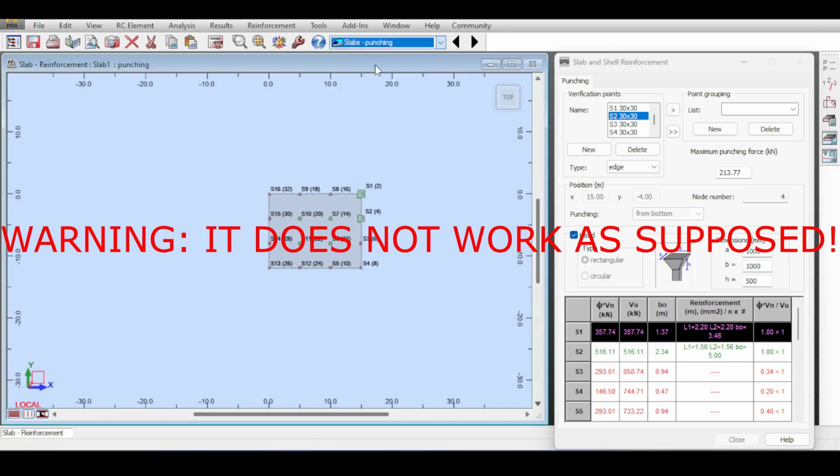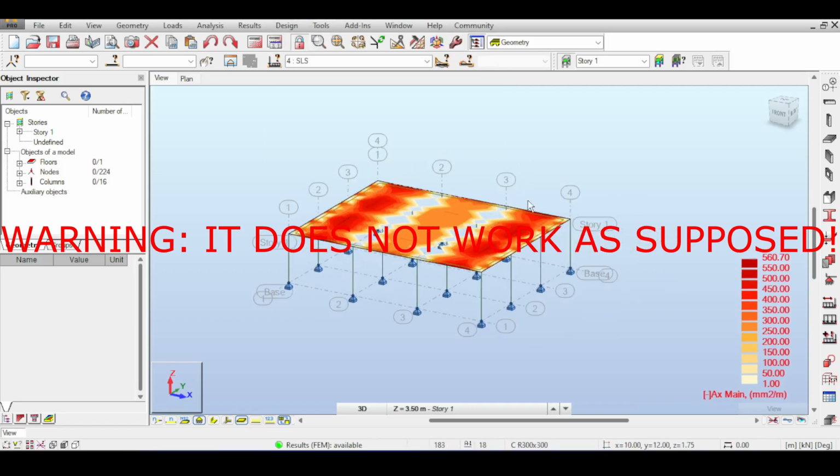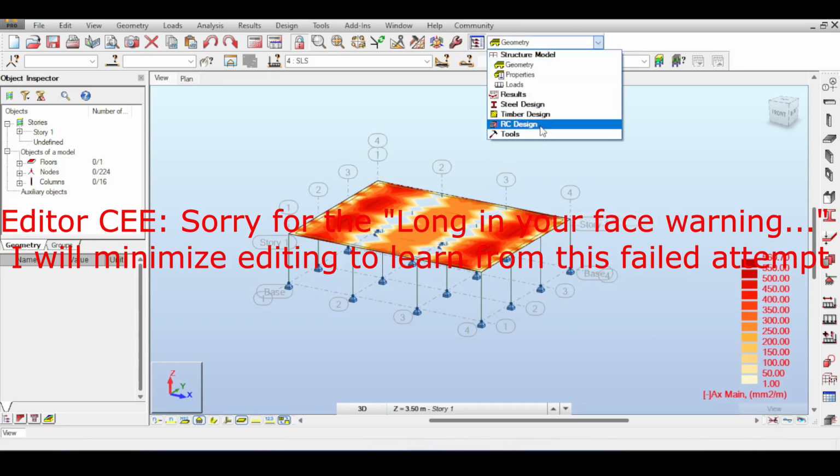Now, to do that, first of all, if you decide on making drops, then this means that you are basically doomed. You should have done this in the beginning. What I'm saying is, if after all this work you decide to do drops, then you will have to rework most of what you've done before. It means that your entire slab system is to be scrapped and you have to start all over again because drops need to be drawn again.